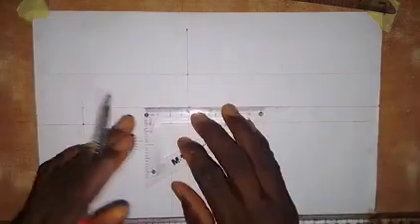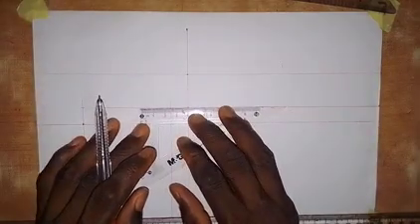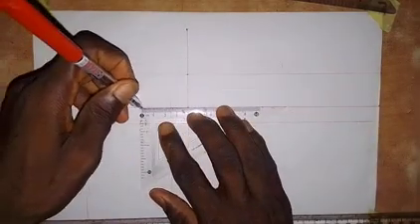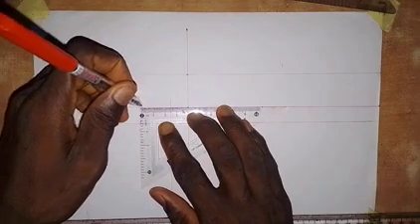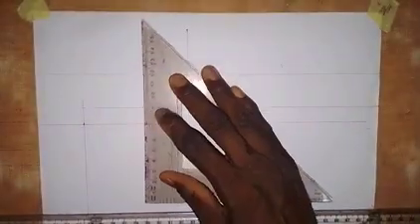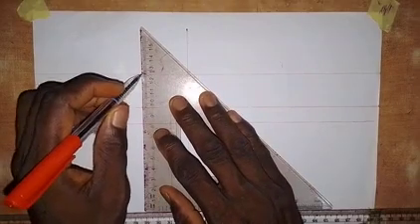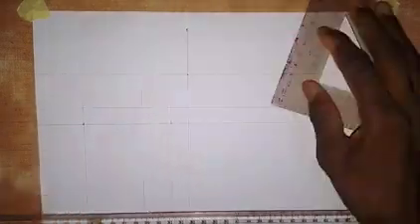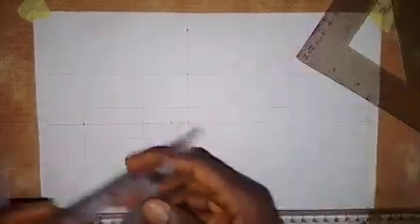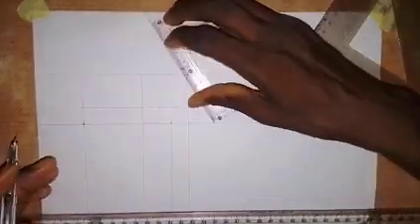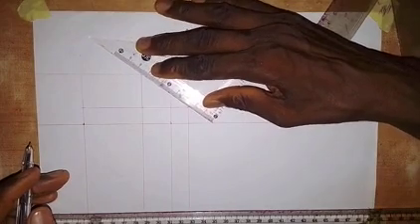So this is what I mean by what I said. So let's take 40 millimeters inward. So this is 40 millimeters here. So at this point I will draw a vertical line. So we'll draw a vertical line from here down. Okay, so I can bring out that slant line, which is a non-isometric line.